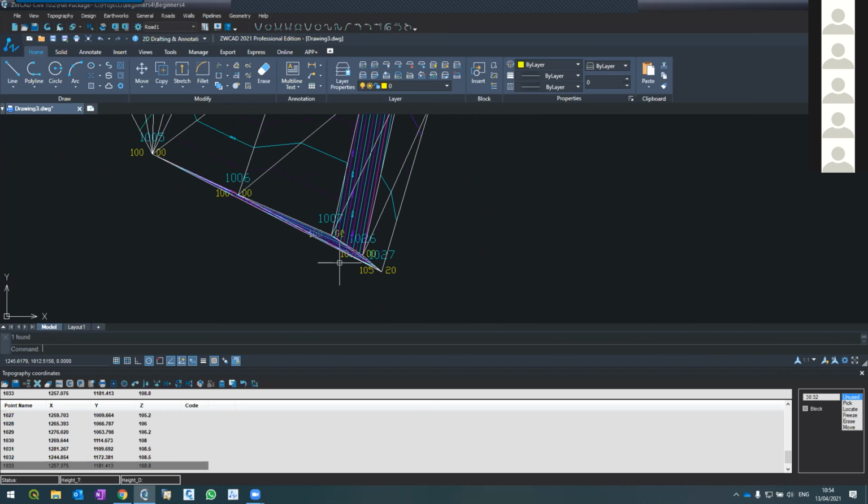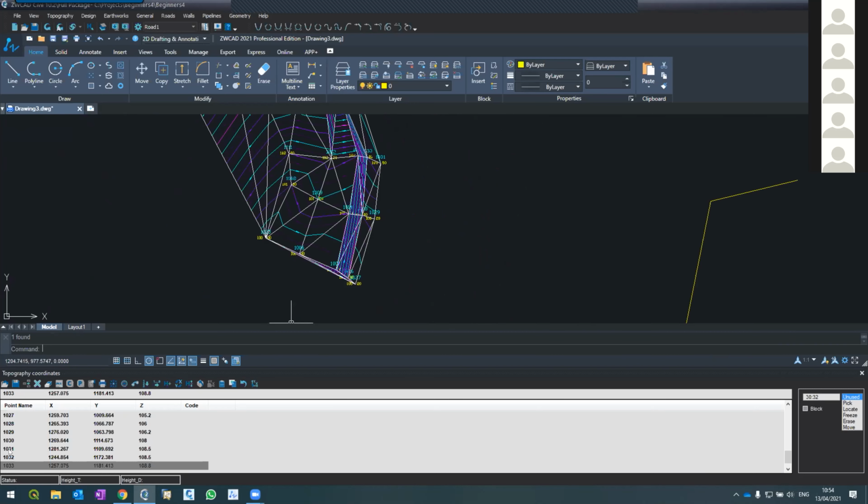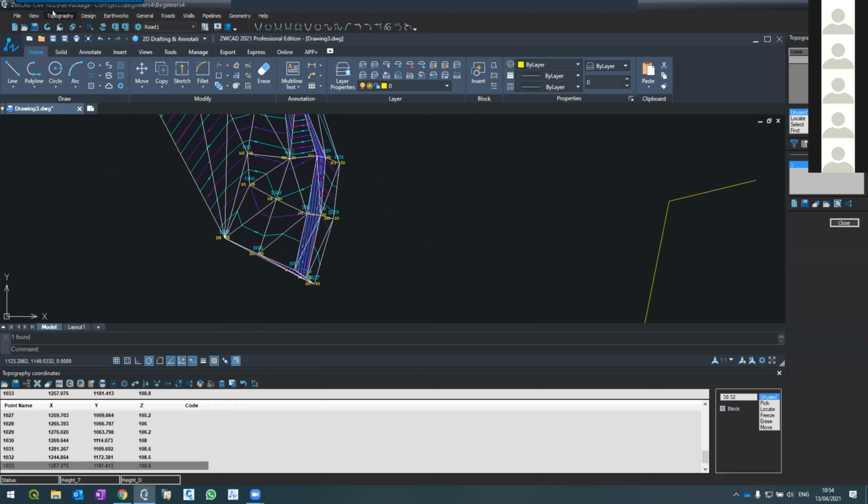So when I come to the office, I download all the points, refresh, get the points. Then I go to Topography Lines. Again, Topography Lines. And what I do, either I enter the serial number of the points which I know, which create the lines of the bottom and the top of the cliff, or I can even locate them here.